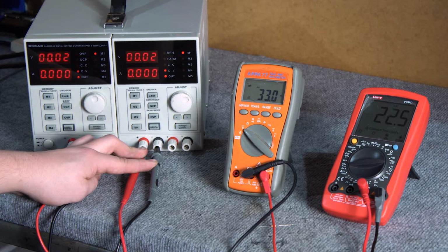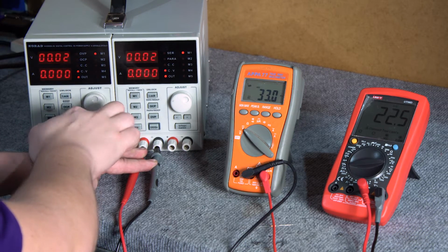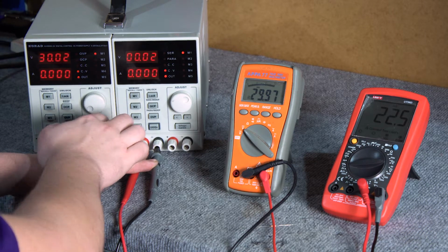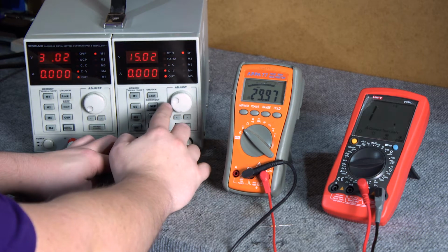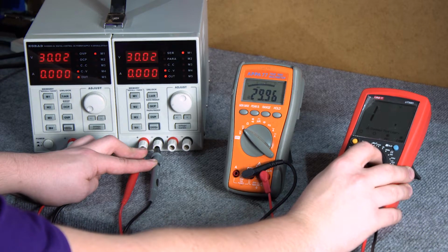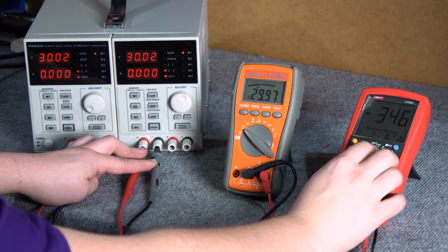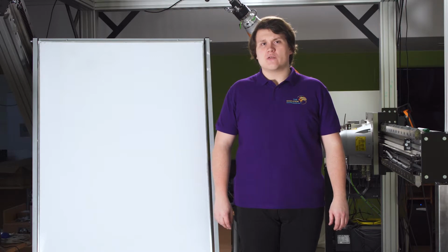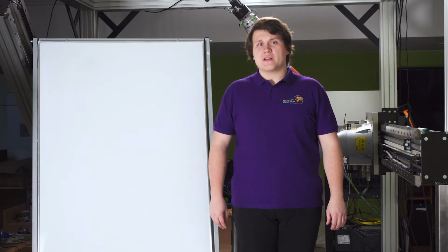It is also very important that when measuring the alternating voltage, an ordinary meter will have high accuracy only for sinusoidal voltage and specific frequencies, hundreds of hertz. If we need to examine signals of a different shape or higher frequencies, we will need a meter that measures the RMS value, true RMS. A multimeter is a very basic and useful device for measuring and diagnosing systems. But before we start to work with it, we should know what quantity we are measuring, to what terminals the probes should be connected, and how to turn on the meter.